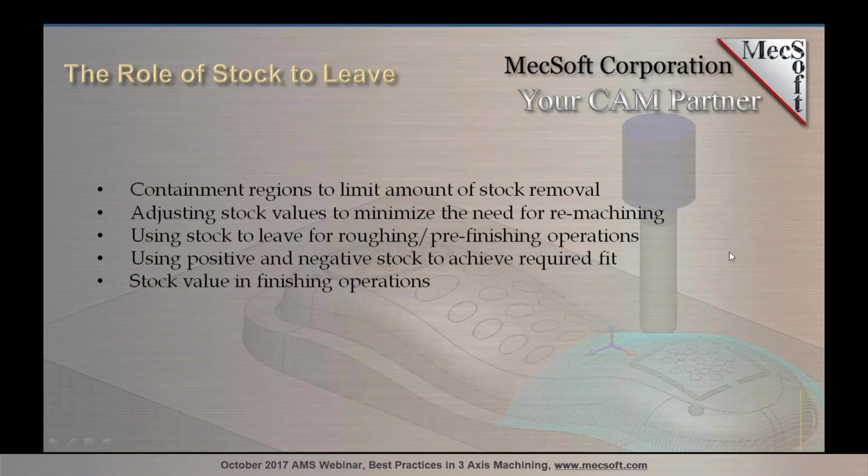And you can also use the stock value in terms of finishing operations. Generally, it's good practice to leave the stock value at 0, but you can also use the stock value in finishing operations. For example, you can use it for roughing or pre-finishing by simply adjusting the amount of stock to leave. So the role of stock to leave is a pretty important role when it comes to your settings, and Uday will walk through and demonstrate some of these to you.